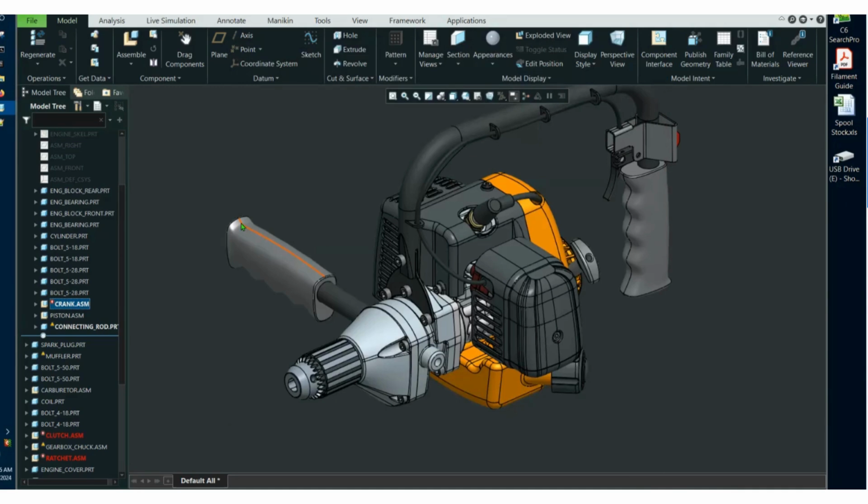Now I could do a replace unrelated, as we previously covered, and it should map in well. But ultimately, we may have this shared across assemblies. This may be a shared component. It may need XYZ crank for the name now, but this assembly is broken by that. The way we get around that without breaking other associated parts that may be looking for XYZ crank assembly, instead of just this drill, is to open up XYZ crank assembly by itself. So here it is in isolation, and of course it has the XYZ crank name.